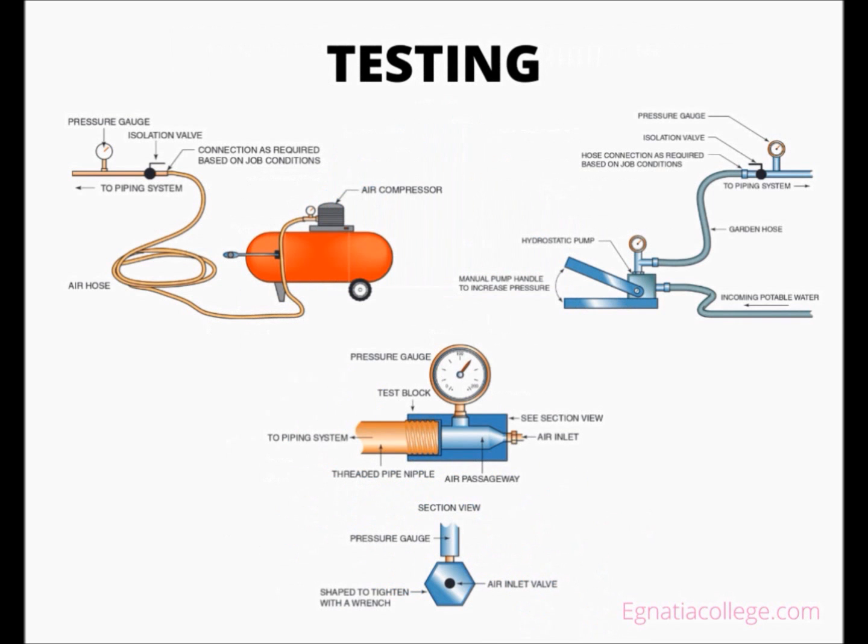Testing. Testing a water distribution system is mandatory. The pressure applied is dictated by code. Most cold weather regions use air tests during colder months, so the piping system will not freeze. Most codes dictate the duration of a test, and, because an inspector is usually not required to remain on a residential job site very long, most tests are only 15 to 20 minutes long.